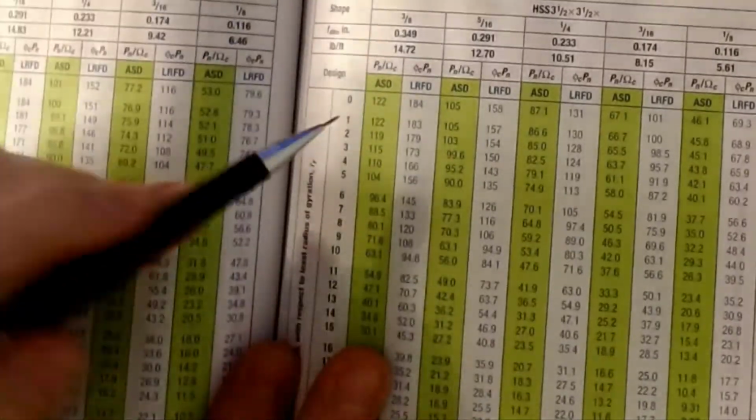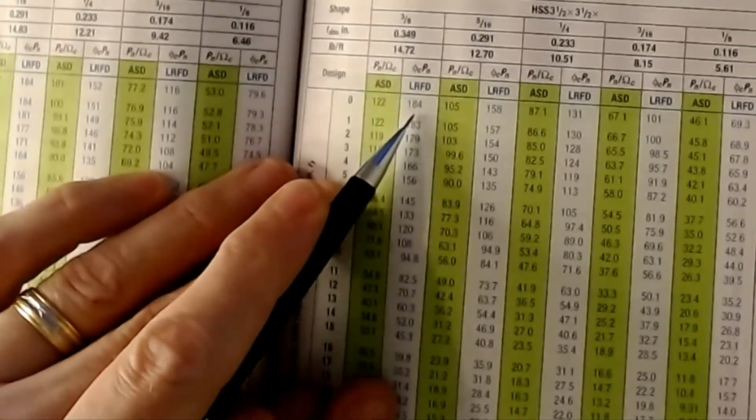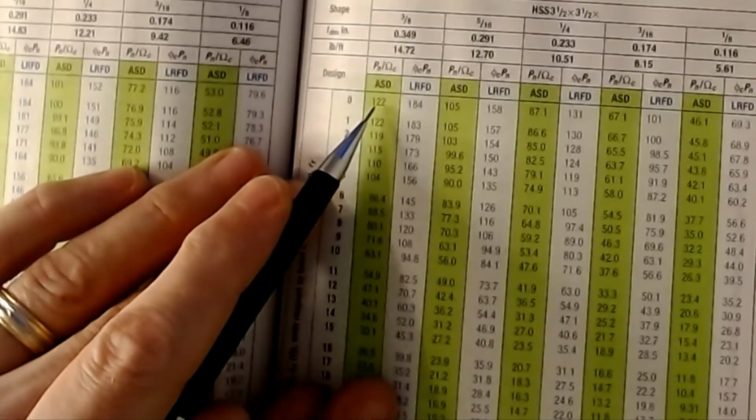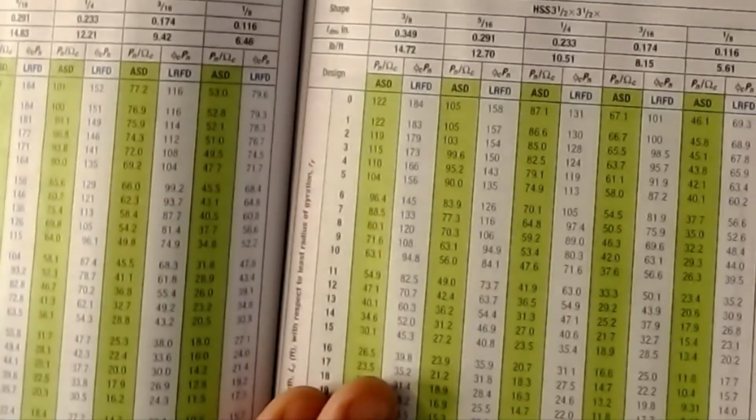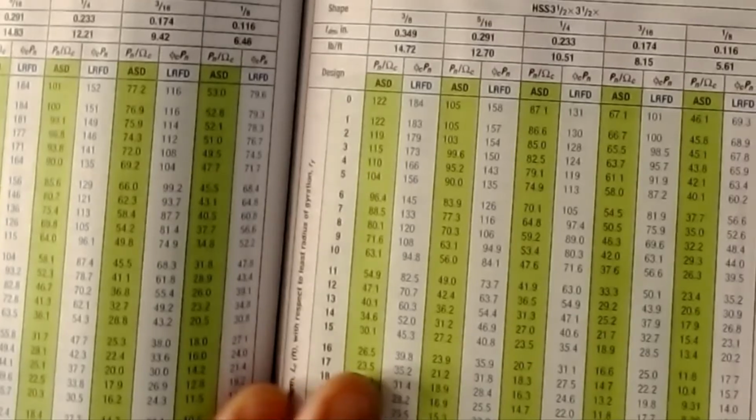And you can take a look at it. That 1.67, if you come back and look at one of the numbers I had on there, for the case we're looking at, take a look at these two values. It's a very short value, right? 184 to 122 is about 1.5, 1.6. So that's in the realm of what we're seeing in the comparison between LRFD and ASD.